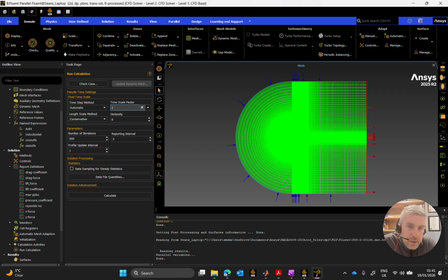If it's a case I don't need a record of what's going on, I just write it in the named expression. So from a mesh convergence study, that's all really we're looking at, our mesh independence study, apologies, and we're just looking at final values whenever a residual or an iterative error allowance or tolerance has been met. And we're only looking for the final answer. It's fine to do them in named expressions.